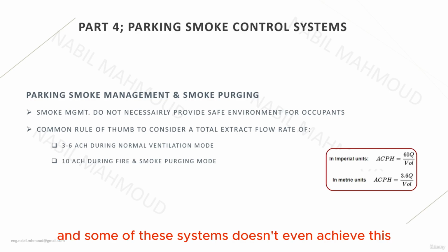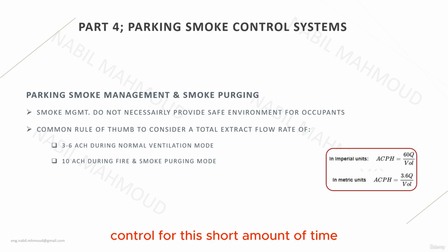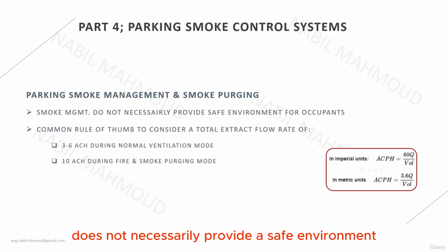And some of these systems don't even achieve this control for this short amount of time, because they are poorly sized. However, you need to understand the difference between smoke management and smoke containment. It needs to be stated clearly that smoke management does not necessarily provide a safe environment for the occupants during the entire fire duration.